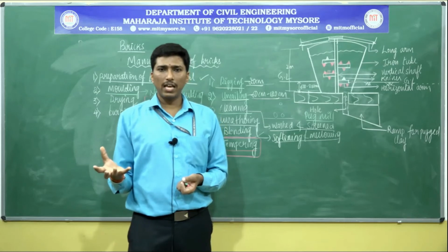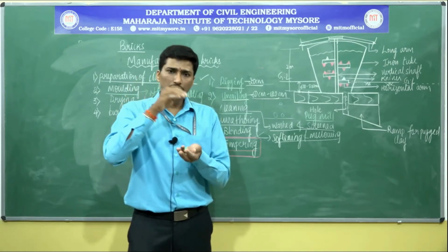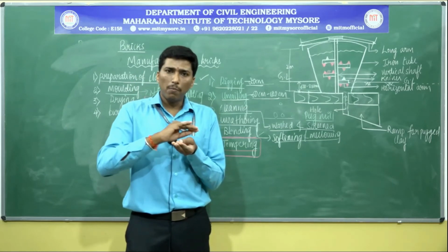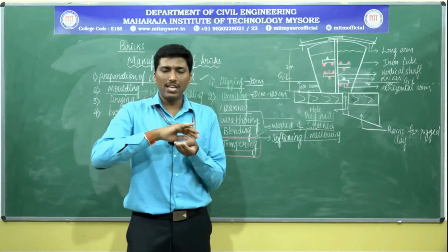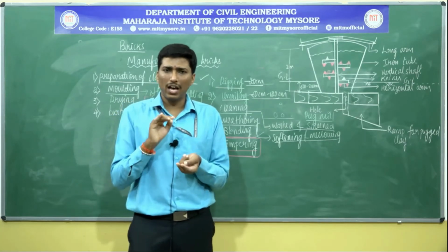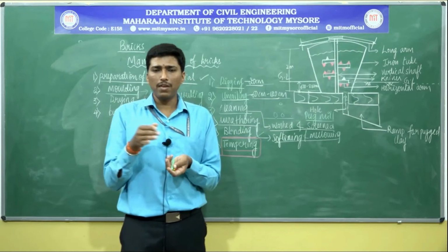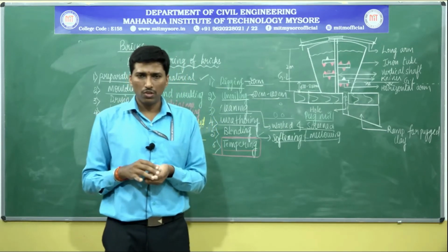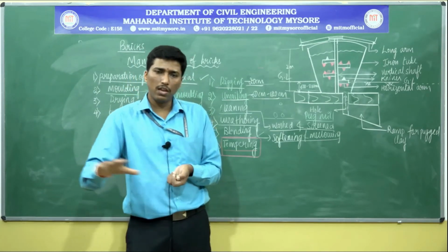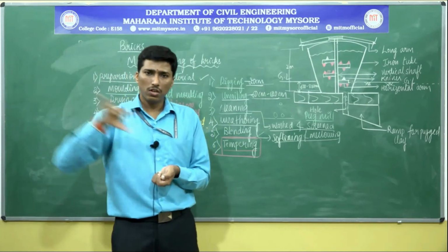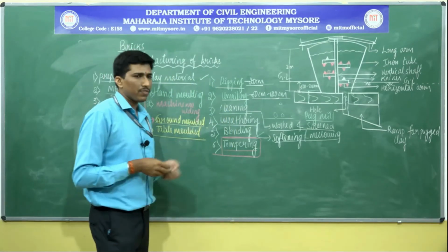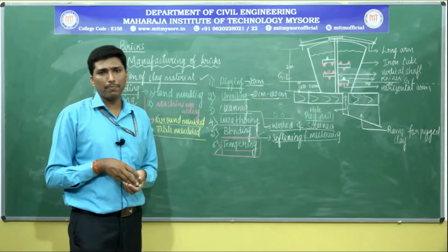The pugged portion of the clay is taken, forced inside and stacked, and the surplus clay remaining above the mould is struck off using either a metallic rim, another striker, or a wooden striker, so that the mould can be used for the next moulding. Likewise, this is completed over a rows basis. This type of moulded brick we call ground molded bricks.